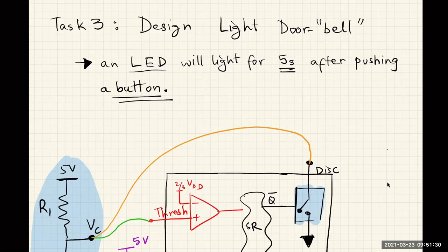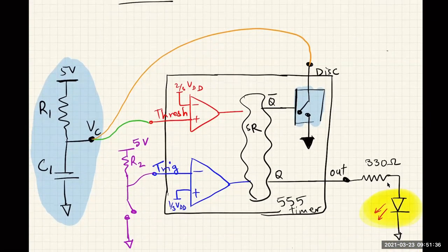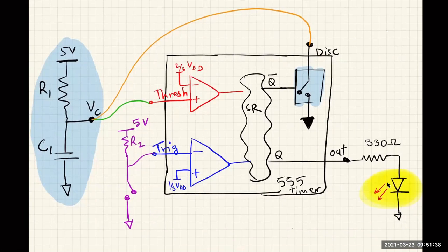What we're using to make the circuit is a simple capacitor charging circuit coupled with the 555 timer. There's a circuit schematic shown in your lab manual that gives you the full circuit that you need to construct. But in order to explain, I'm just going to take parts of this circuit and ignore some of the parts that don't contribute functionally, but are equally important.